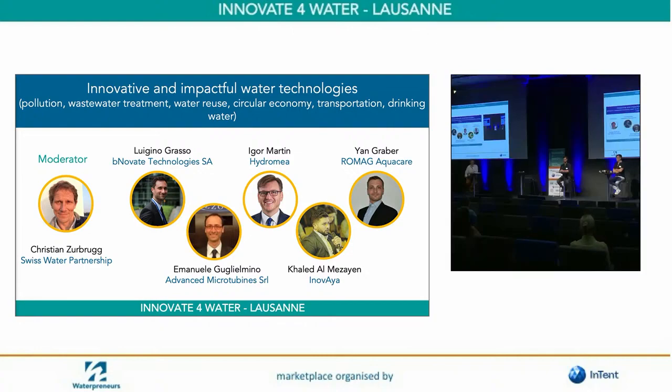With the low energy downstream water, actually what happens, the turbine to spin needs to have a pressure drop which is already present in the process, which means if you have a valve which is already there for whatever reasons to adapt the pressure to the users, there you have a pressure drop, which means energy wasted that can be used for free by activating the turbine.